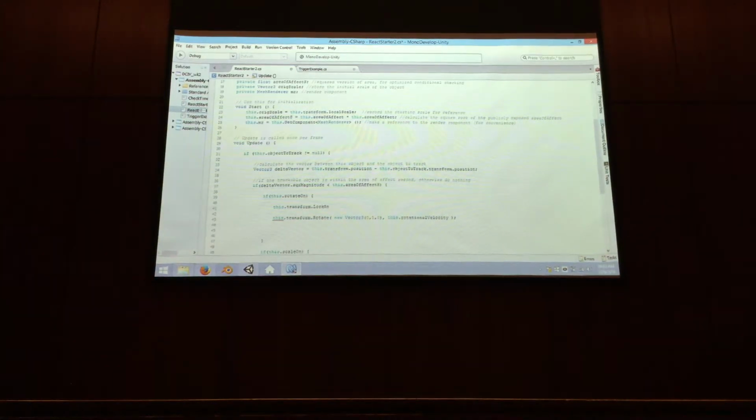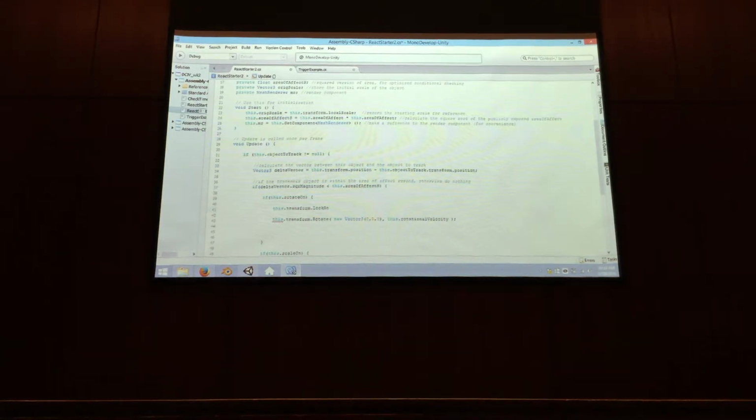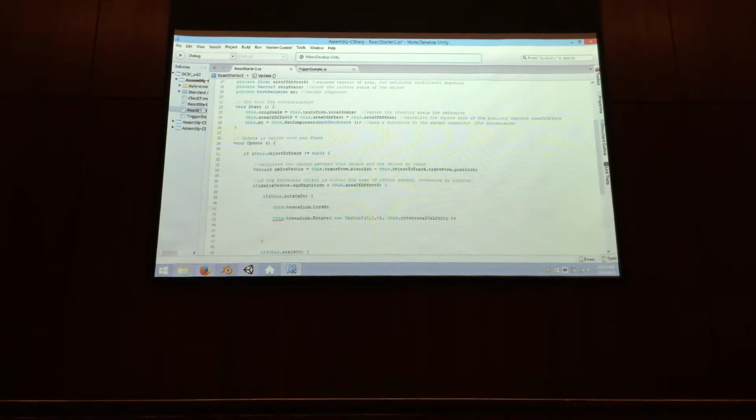You guys should know now about mapping and about opacity maps, right? So if you take a material like a tree and you have the brown and the green and the raster image, and then you add an opacity map to it so that the alpha channel has black all the way around the tree, then what we see when we render is we don't see any of this because that's all transparent.